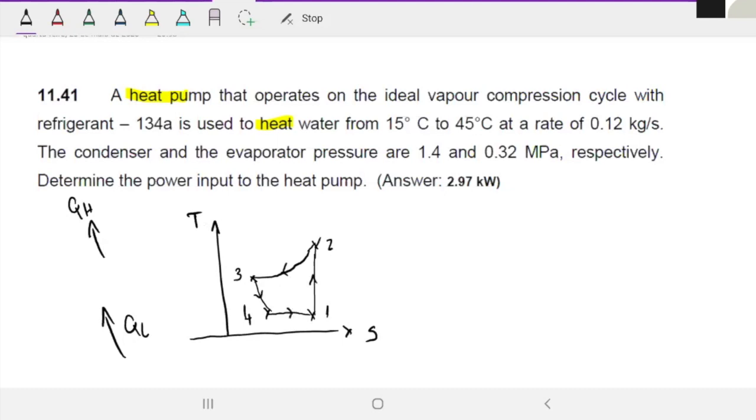This is the normal, let's say, refrigeration cycle. Here we're giving work to the system. Over here we're extracting some energy. Over here we're giving out some energy, right? That's what the QH and QL is. Now, if you have a fridge and you want to keep the inside of the fridge cold, the inside of the fridge is going to be over here, right? This green part's my inside of the fridge. So whenever this guy extracts heat and then goes and releases the heat outside, I'm maintaining that guy cold, right?